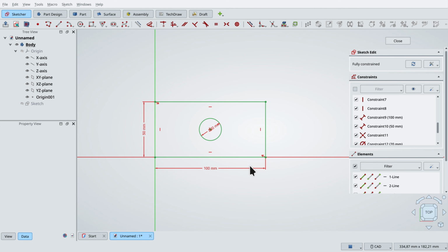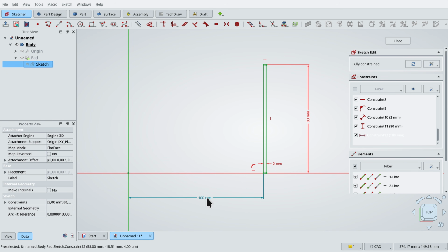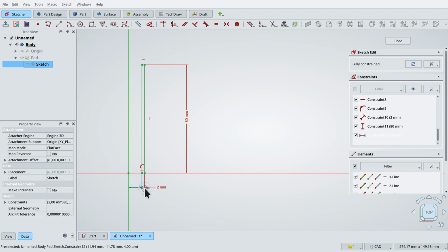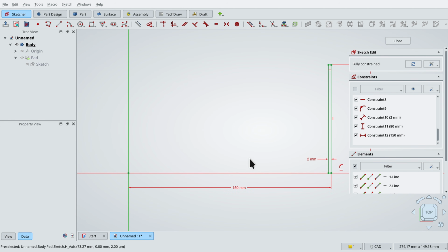These are the core fundamentals of the sketcher: creating shapes, constraining them manually or automatically, and using logical relationships to build a smart model. However, I want to draw your attention to how you choose to constrain certain elements. There's a big difference between a sketch that is simply green and a sketch that is built to be robust and easy to modify later on. One area where FreeCAD sometimes struggles is determining whether a dimension should be positive or negative, especially during significant changes. In this example, I have a 100 mm gap between the origin and my rectangle, and the rectangle is 2 mm wide. If I change the spacing from 10 to 150, the 2 mm width might suddenly jump to the other side of the line. This is what we call constraint flipping.